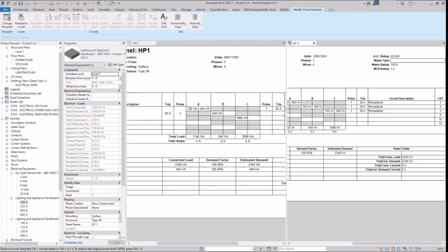Even if it's for a very short time, until a circuit breaker opens or a fuse blows, it's going to be a massive amount of current because there's ultimately very, very little resistance. And we know that V is equal to IR, but if we're looking at I is equal to V over R, and if R is really small, that means I is very large. Tracking that so far? Okay. I know that was kind of weird, but just know that when there's a bolted fault, you've got a stupid amount of current.